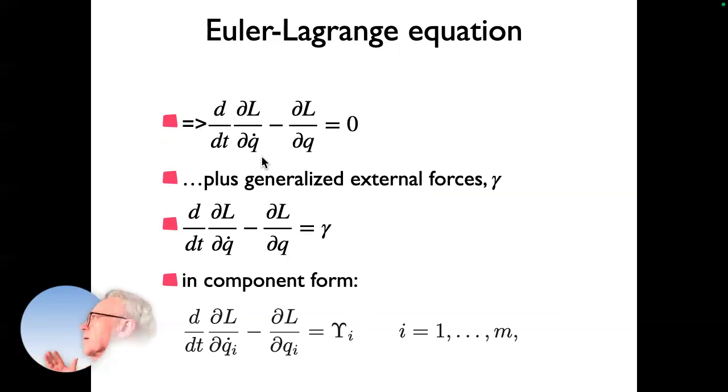So this equation as such, you couldn't immediately maybe make sense of it, but that is essentially the equivalent of the Newton equation in Lagrange calculus. Now, in practice, we're using a variation of this approach, because in practice, we're not having conservative systems. We may have friction. Some of the models have friction, but we also insert these torques right into the system. And these torques are essentially deviation from 0. There's an insertion here of external forces, and the nature of these forces depends not on the variables that you choose. So if we have joint angles, then we can identify what is on the right-hand side. It will be a torque that's on the right-hand side.